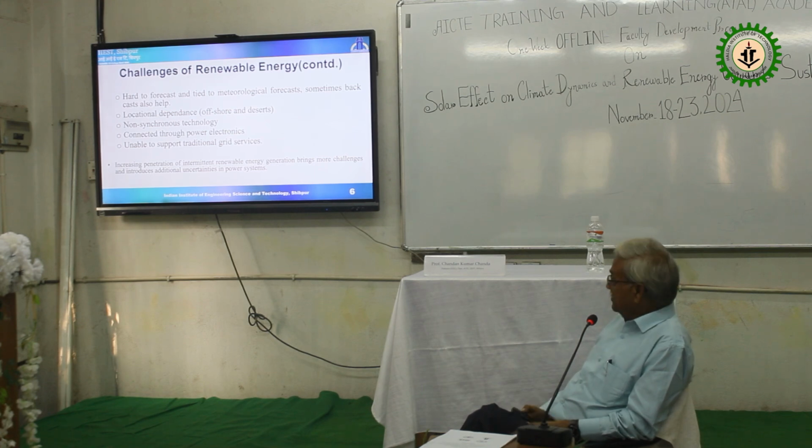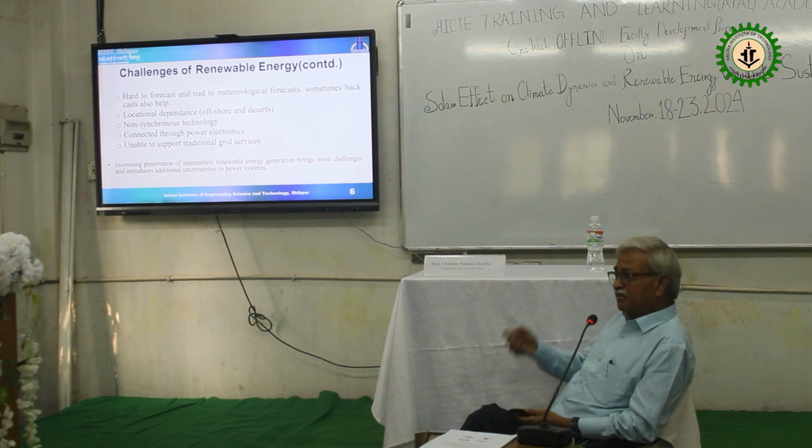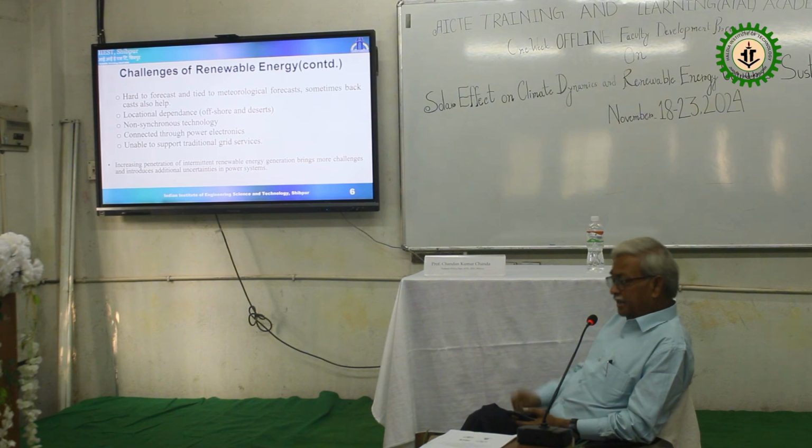Non-synchronous technology, zero inertia, connected through power electronic devices. Again the question is your transmission line, which is AC. We are generating DC energy, so a power electronic device will come in between DC generation and AC transmission, and in the back of our mind a lot of questions come up. A power electronic device, in layman's language, is nothing but a switching device. And any switching device in electrical engineering creates harmonics.